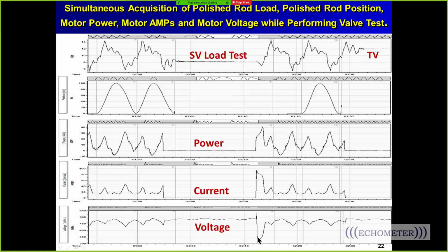And why is it dropping? Well, the transformer where the energy is 480 is far away, about half a mile away, and the energy has to flow through the line to the well, and you see a drop in volts at the pump unit, and the volts over at the transformer is still 480. So this is called line loss. You can use this to calculate the line losses.